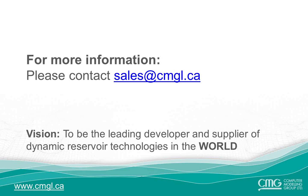So the next question is from Chanta Salma, and the question is, how is leakage of fluids modeled during hydraulic fractures into over and underburden in CMG software? So what we would need to do is incorporate the rock within that overburden and underburden. Really anywhere where the fluid can flow, that fluid will move. So if there is enough permeability in either the natural fractures or in the matrix, the fluid will just naturally flow based on the pressure gradient.